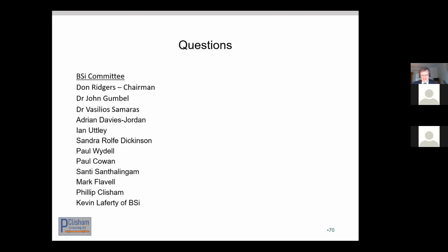Yeah, you also go on, sorry, I missed the last bit of the question, asking whether you feel it might need some light or high compaction for the surround and the embedment. It depends what you're using. If you're using a self-compacting material, no. If you're using something like a sand, yeah, compaction certainly helps as long as you don't overdo it. You do a lot of damage over-compacting, and this is a balance you've often got to achieve, certainly with the more flexible pipes than you're dealing with in that case.